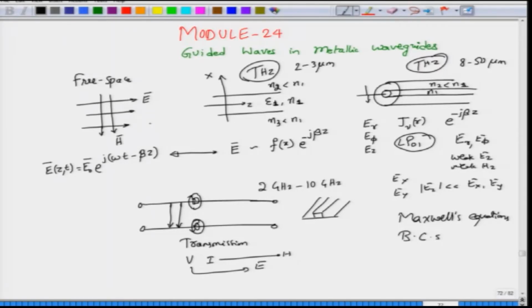So, you do have different structures which are tailored for different frequencies, simply because some structures are useful in squeezing the modes at those frequencies, whereas if you try to make the same structure for other frequencies, then the required geometrical parameters will be so huge that it would be impossible or impractical to build. Okay. So, this is all guided waves that we have looked at.